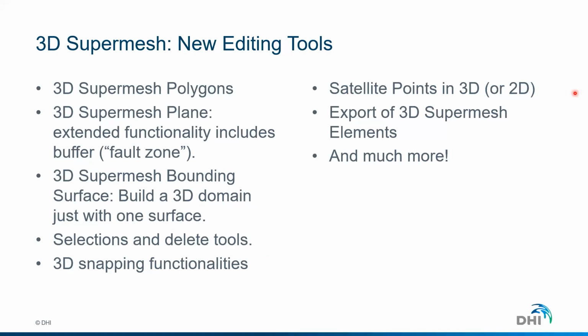This is the case in 2D, especially for those working in the geothermal sector. If you remember, we use this rule of ideal element size a lot, where the size of the discretization around the borehole depends on the radius of the borehole, which you will typically manage by creating auxiliary points. So now we have a nice tool which allows you to automatically create these points in 2D and 3D.